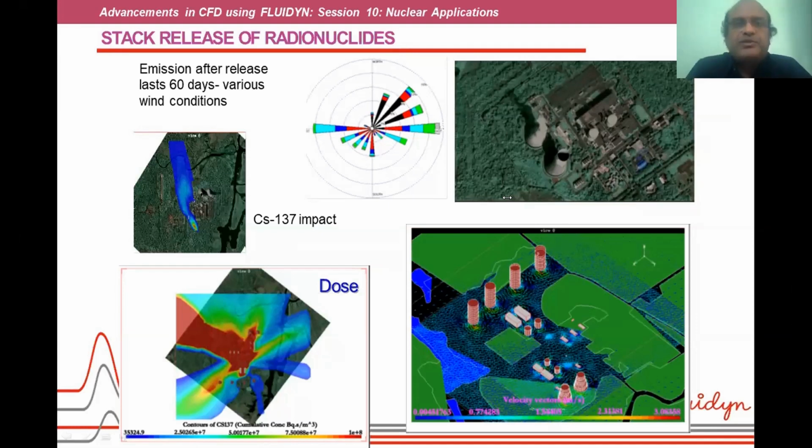Actually, whether the flow is Newtonian or non-Newtonian depends on whether the viscosity depends on the strain rate. For liquid metals, I have not worked on that. I need to check which properties are used. But if it is non-Newtonian, it can be considered. I think it would depend on temperature. For example, if you take lead, above a certain temperature it will behave more or less like Newtonian. In some temperature range, it could be non-Newtonian.